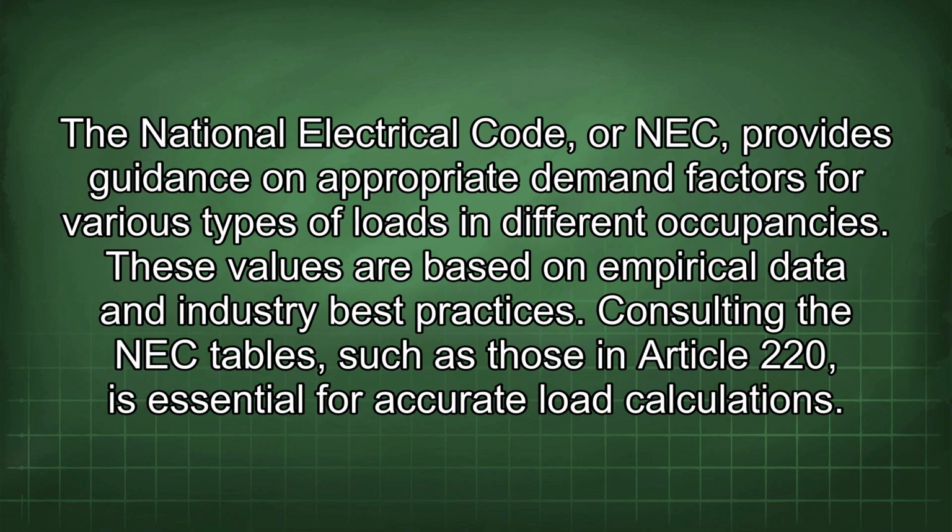The National Electrical Code, or NEC, provides guidance on appropriate demand factors for various types of loads in different occupancies. These values are based on empirical data and industry best practices. Consulting the NEC tables, such as those in Article 220, is essential for accurate load calculations.